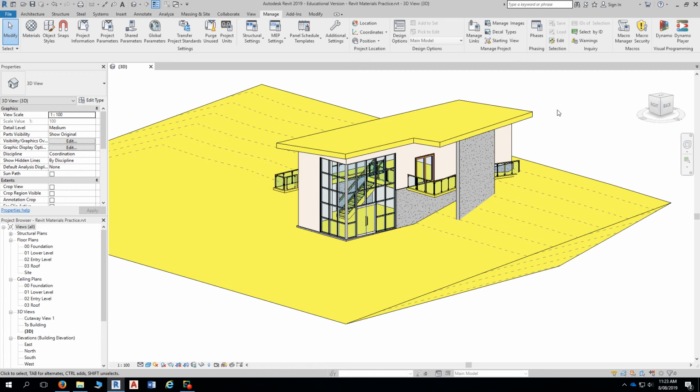So we could perhaps present our virtual Revit model in all white to represent an architectural foam core model, just for a concept design, for instance, given that we're not going to specify colours or textures at this stage, just purely from a design point of view. And we can use the by category method to do that quite quickly.